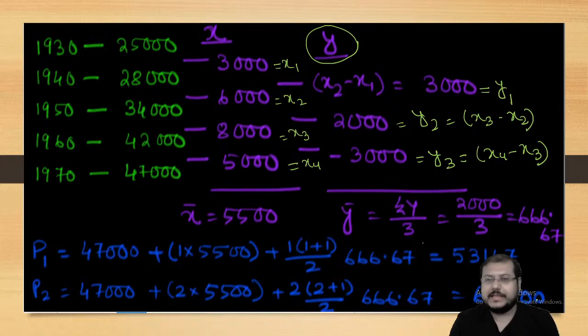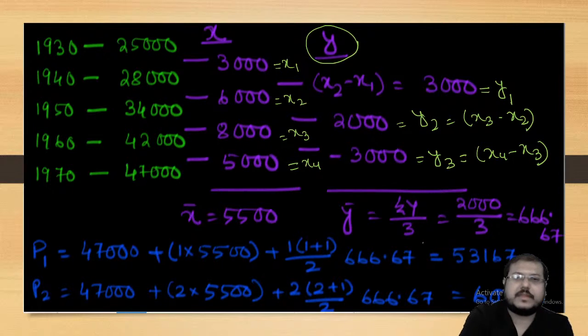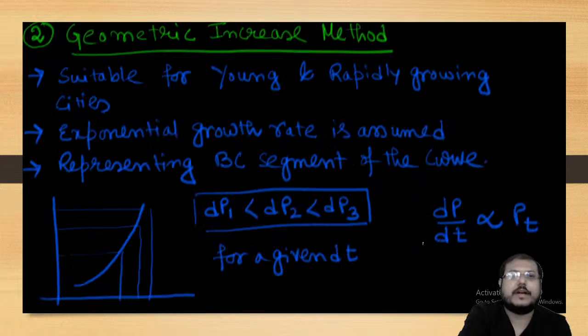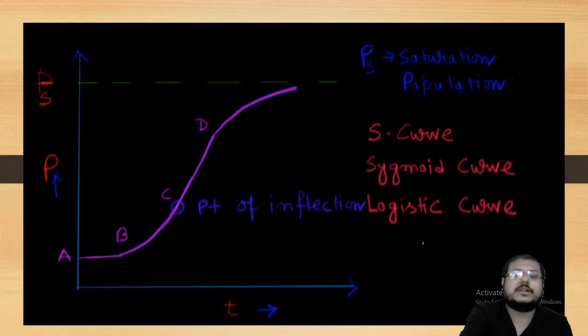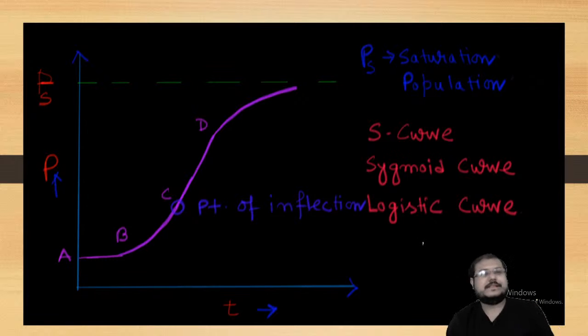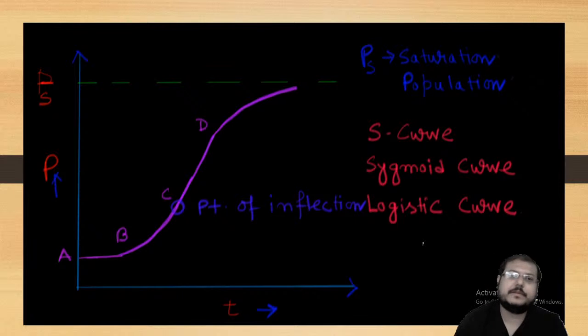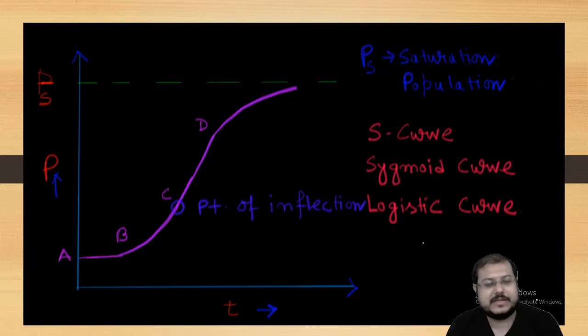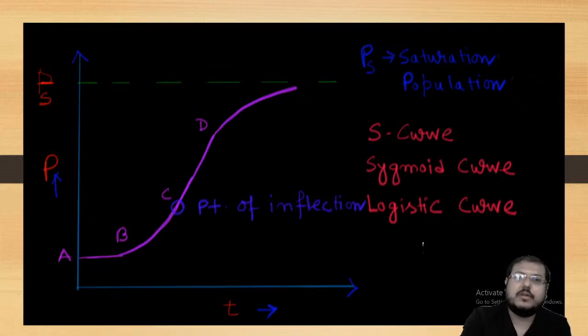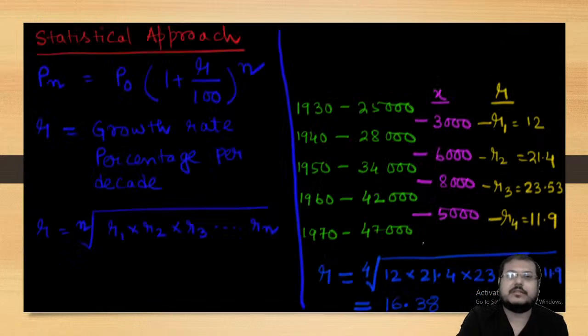Okay. So for the confused growth rate, no portion of the curve is provided. If you move back to the curve, what is happening? In the AB segment, as dP/dt is almost zero, P is constant and no population forecasting process is required. For the BC segment, the geometric mean method is used. For the CD segment, the arithmetic mean method is used. For the confused growth rate, the incremental increase method is used. Beyond point D, there is one particular method called the decrease in growth rate method. Now, we are going to discuss that method.